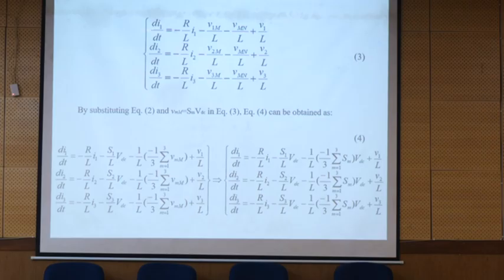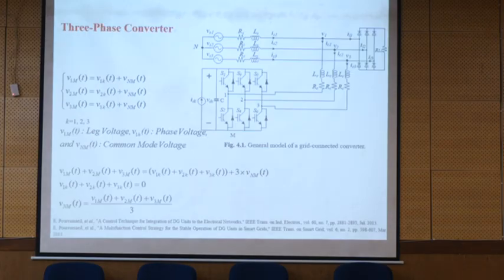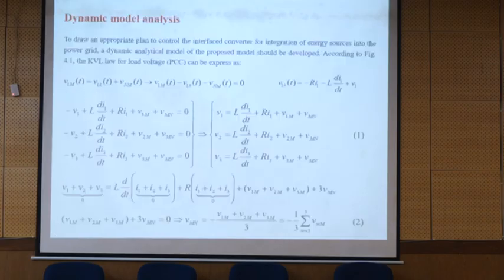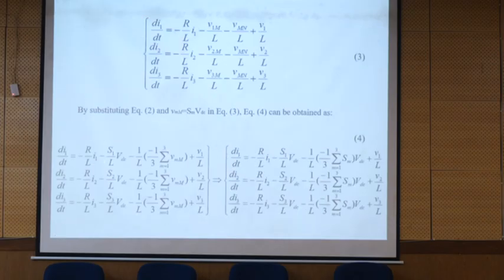So this is di/dt. This is R over L times i minus V1M. V1M is the voltage of the converter here. So it is like S times VDC over 2. So we go here and put S1 VDC instead of V1M. Do you agree? Okay, good.